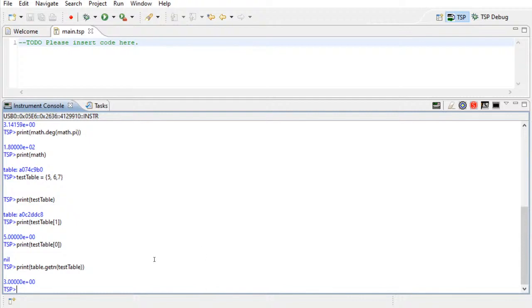Now, let's start talking. All of this hasn't been anything specific to the instrument. This is just basically Lua backend. This is all coding straight in the TSP Lua side of the language. So let's do some things with the instrument itself. Earlier we did star IDN. So TSP has its own methods for getting information on the instrument. One of the best ones is called local node, which is another table, localnode dot, and let's print out the model number of our instrument. And we see that it is indeed a 2636B.